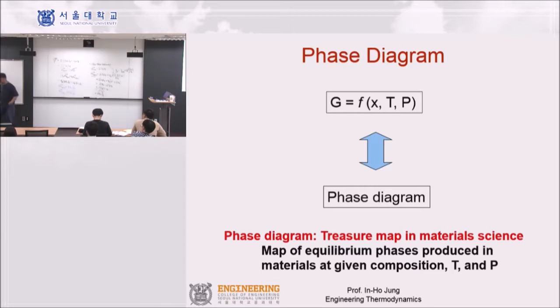Once I know this, I can back-calculate all of that, and the same thing for the phase diagram. There is a one-to-one relationship between the Gibbs energy and the phase diagram. We're going to learn a lot about this. And in some of the exams, I always ask this kind of question: when you have this kind of phase diagram, what is the regular solution parameter of the liquid phase or solid phase? You have to expect this kind of question on your final exam.